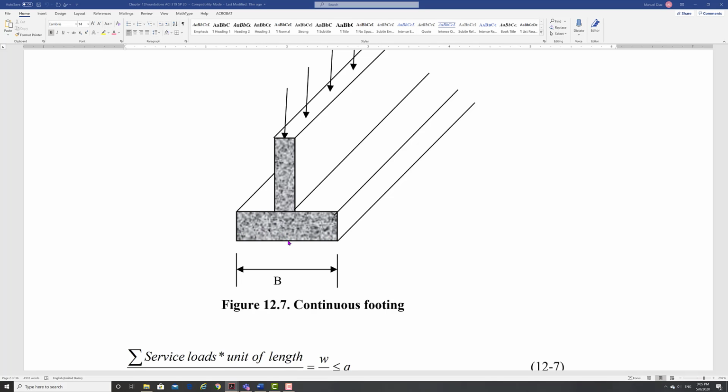But if you just imagine you're turning this all the way around, and this becomes the top and this becomes the bottom, it's like having a wall supporting a slab. You're putting your loads here because that's your soil, so it's like applying this vertical load on your slab, and you are bending this as a cantilever going that way. Your tension side is this one.